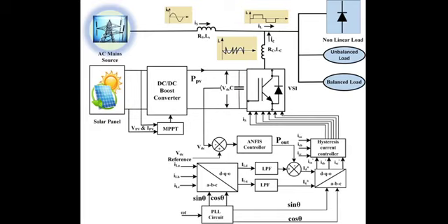High-pass filters. High-pass filters can be used to filter out low-frequency components in the system's output. They are used in specific cases where low-frequency content may need to be removed before the electricity is fed into the grid. Notch filters. Notch filters are used to attenuate specific frequencies or frequency ranges. They are employed when there are known frequency components or interference that need to be eliminated from the system's output. Anti-islanding filters. These filters are a critical safety feature for grid-connected systems.